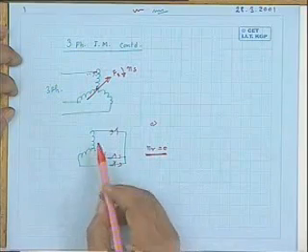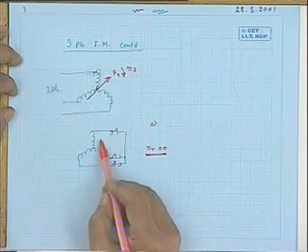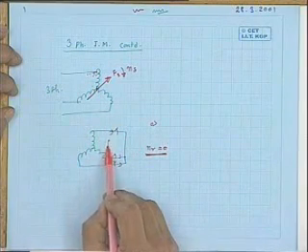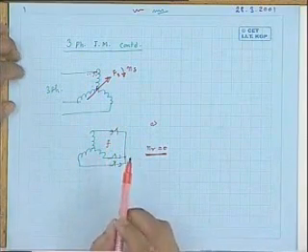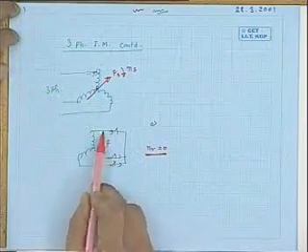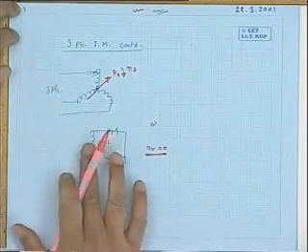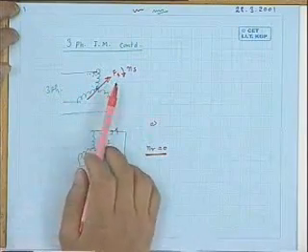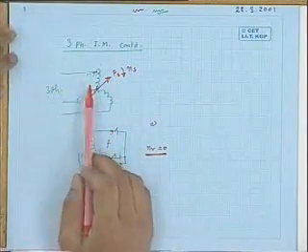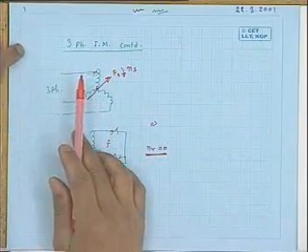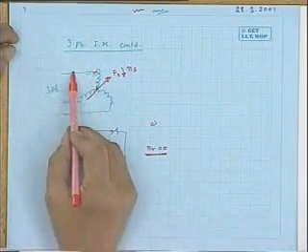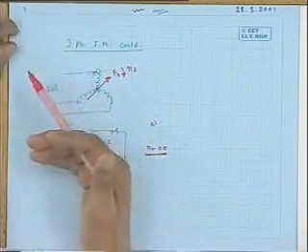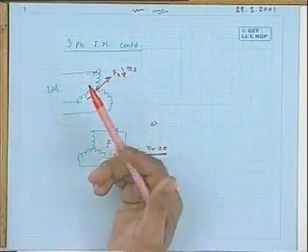Then the rotor field too will rotate with speed ns, because at that time the frequency of the current is f. So there will be additional MMF coming in the machine. But the flux per pole cannot change because it has to satisfy KVL on the primary side. Therefore, the stator will now draw additional balanced three-phase current from the source.